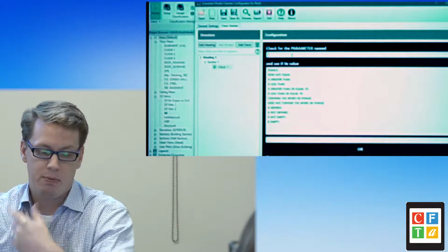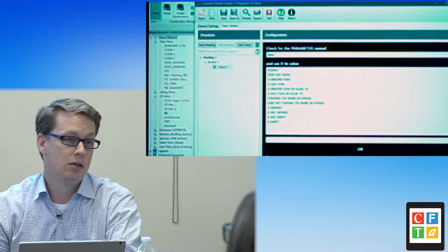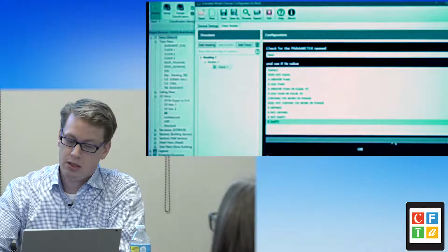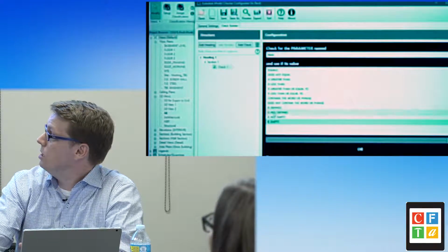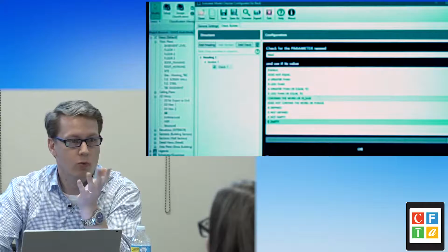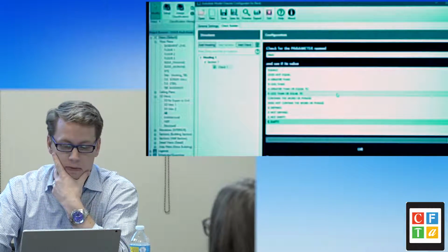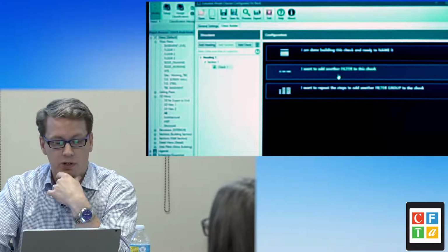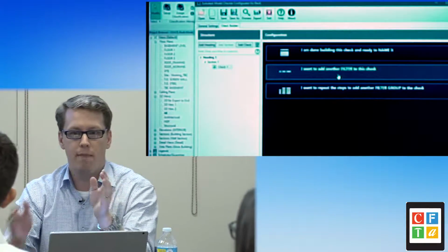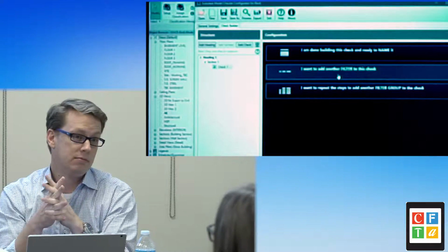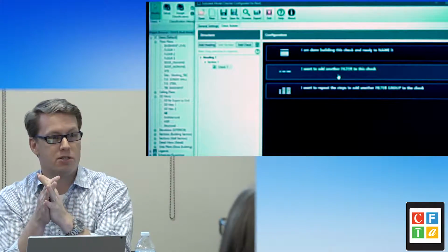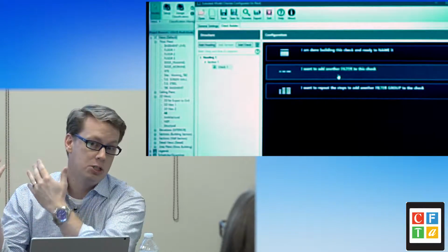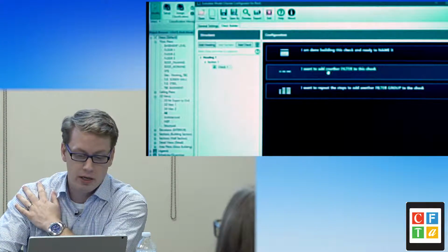And so I could type in what that parameter is. The parameter is called mark in Revit. It's pretty simple. And I just want to make sure it's not empty. But you can see all these different ways of controlling what I'm looking for when it comes to a mark. So I could add another filter, and I could say, look for a mark that meets this format. Make sure it's there, but also make sure it's 3 characters or 1 letter and 2 numbers, right? And I can control that by adding another filter in here.